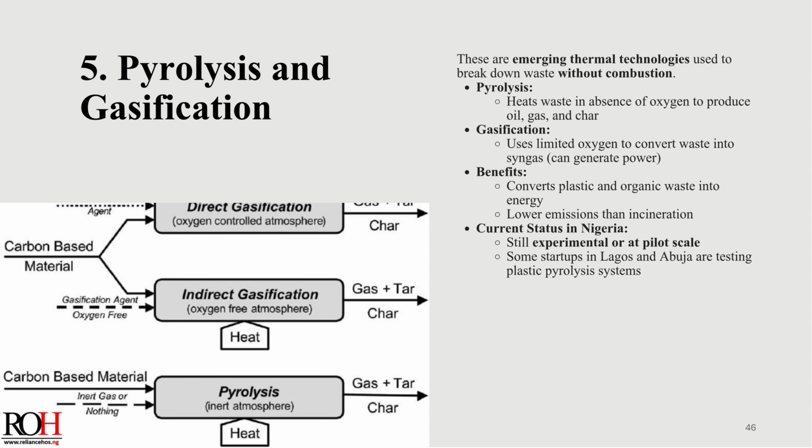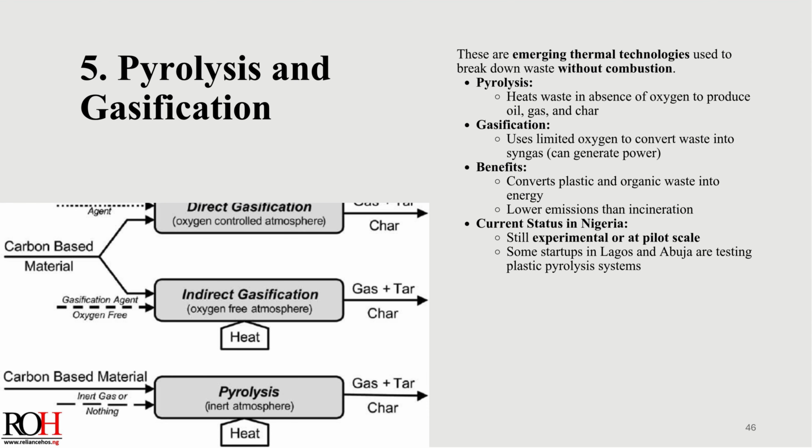5. Pyrolysis and gasification. These are emerging thermal technologies used to break down waste without combustion. Pyrolysis heats waste in absence of oxygen to produce oil, gas, and char. Gasification uses limited oxygen to convert waste into syngas, and can generate power. Benefits: converts plastic and organic waste into energy, with lower emissions than incineration. Current status in Nigeria: still experimental or at pilot scale. Some startups in Lagos and Abuja are testing plastic pyrolysis systems.